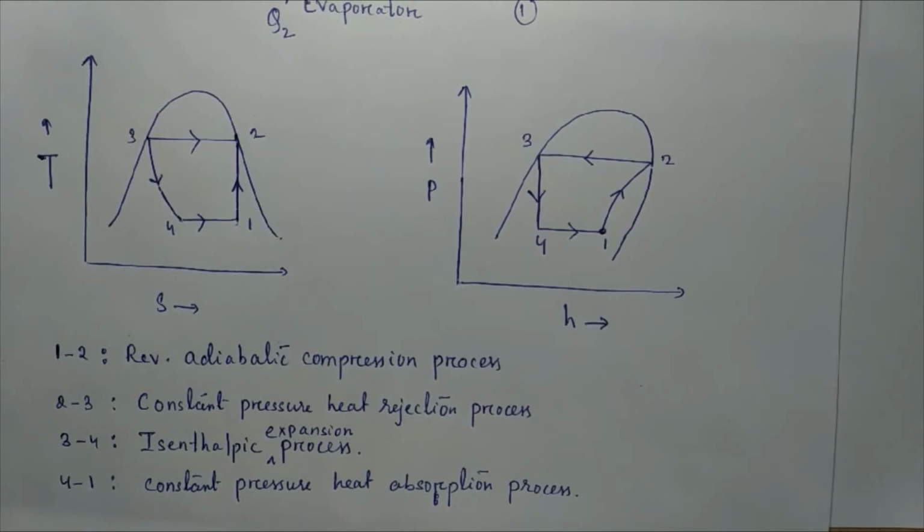Next one is the expansion valve. Now what happens in this expansion valve? The expansion valve is also known as the throttle valve, which we already discussed, or the refrigerant control valve. The function of the expansion valve is to allow the liquid refrigerant under high pressure and temperature to pass at a controlled rate after reducing its pressure and temperature. Some of the liquid refrigerant evaporates as it passes through the expansion valve, but the larger portion is vaporized in the evaporator at the low pressure and temperature.